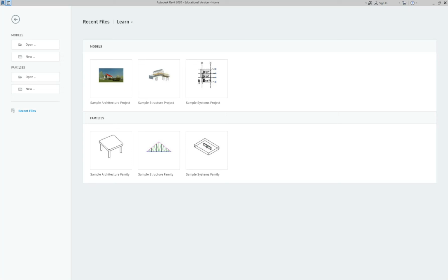No, we don't. So in BIM modeling, we tell Revit, this wall starts at this level and ends at this level, and you might have 4 levels in between. And you can also come in the middle of it, like a partition wall, and say this wall starts here and ends here. So let's just start with those 2 things. Let's consider the construction, and let's consider the levels, all right?